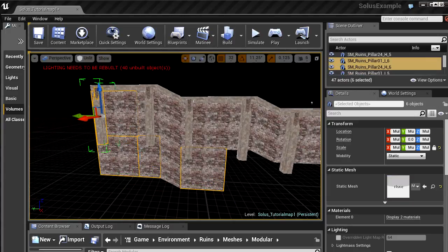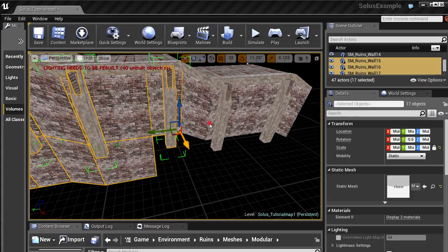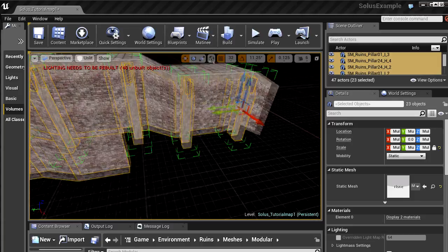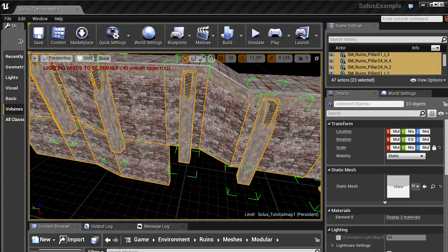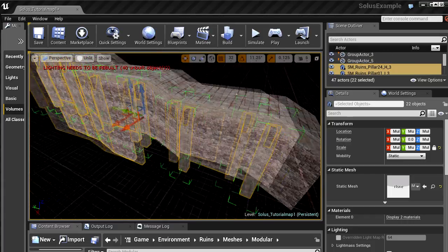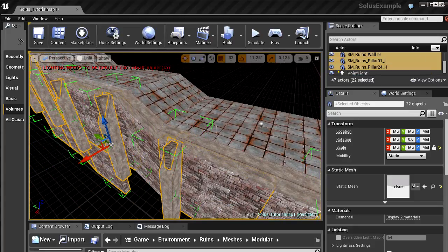Then we want to duplicate it to the other side. So let me just select all the parts that it makes up. And just a tip, I'm selecting multiple meshes using Control. So if you hold Control and you click things, you can add things to the selection or take them away. Holding Control and clicking it again also takes it away from the selection. However, as explained earlier on, Control is also the key used for moving things. It's also the shortcut for moving things.